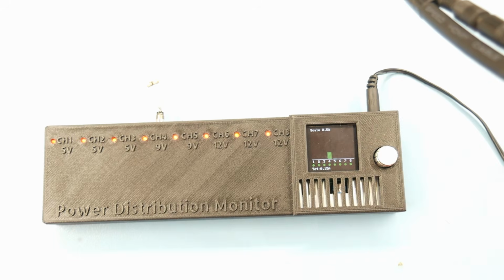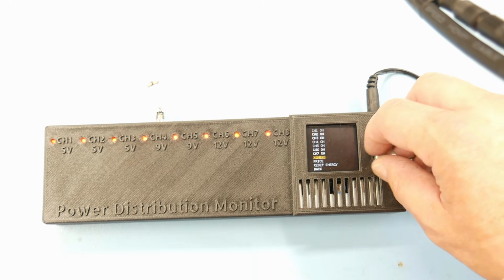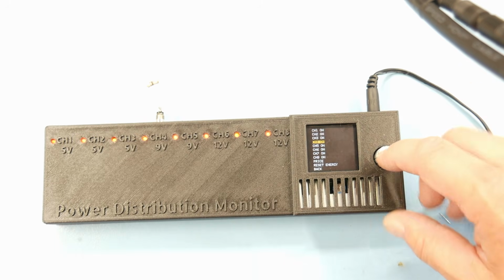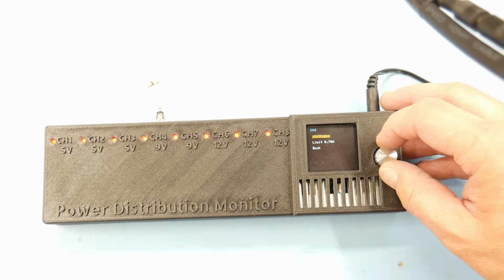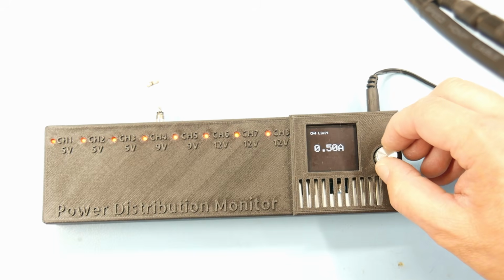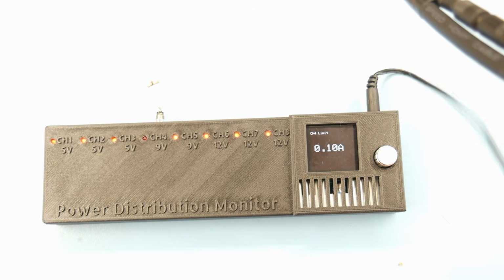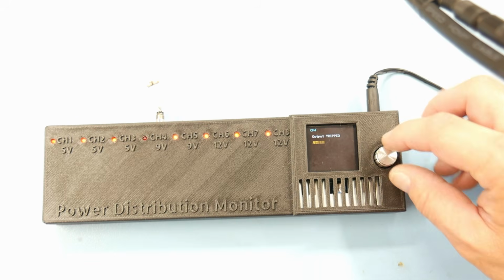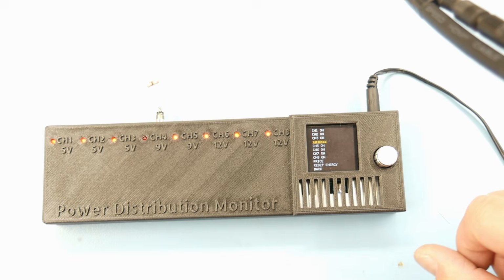Then when I go back to this one, there's a current limit, and I will show you. The minute I set the current limit for channel 4 lower, then at some point it will detect and it will switch off, and you can see that by the LED going off. Now watch closely. Bam. Now it turns off. The LED goes off, and in the main menu it will also show you something. Let me just wait. It will go back automatically, so we test that as well.